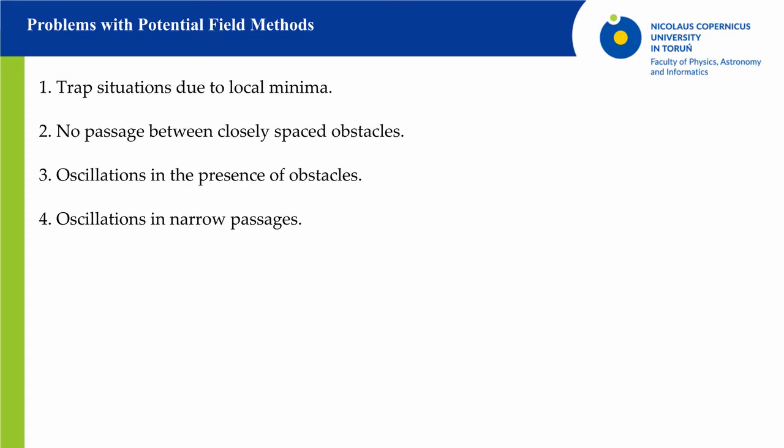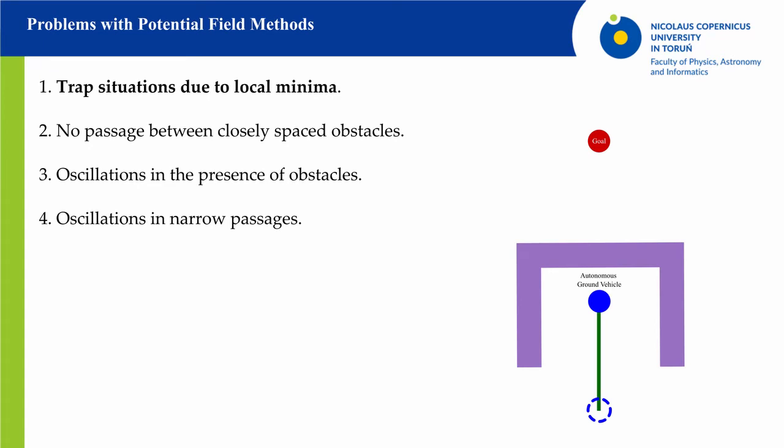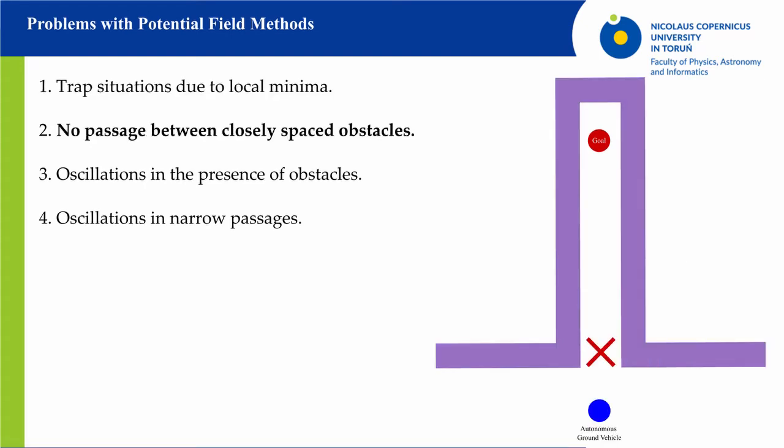Unfortunately, the artificial potential field algorithm has a few problems. The first one is no mechanism of avoiding or bypassing dead ends. In the case of a vehicle going into one, it cannot get out without human intervention or another mechanism. In very narrow passages, the repulsive force generated by the walls can stop the robot from getting between them. In this situation, the goal will not be reached.